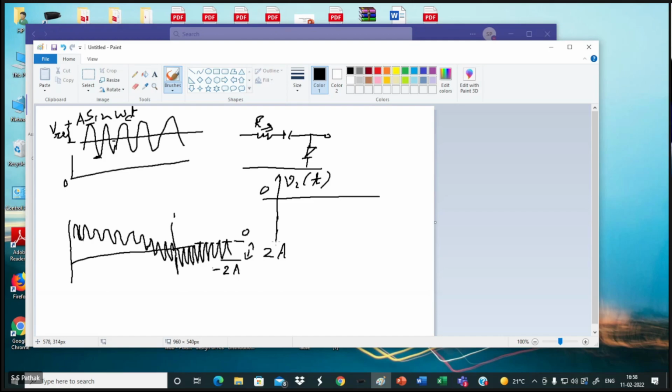So it is coming like this, like this. This is a clamped square wave. Sorry, I made a mistake. This is not 0. Let us say this is minus 10 volt, and my 0 is somewhere here. So at minus 10 volt, it is appearing like this.